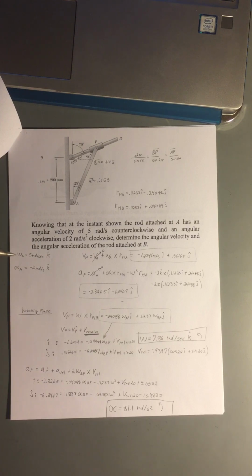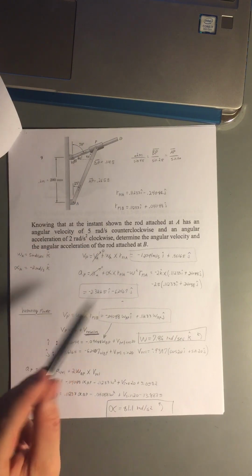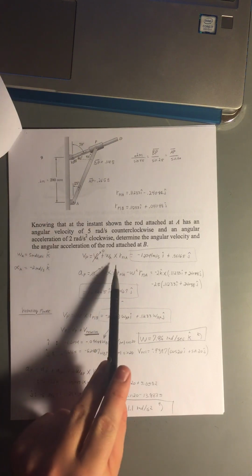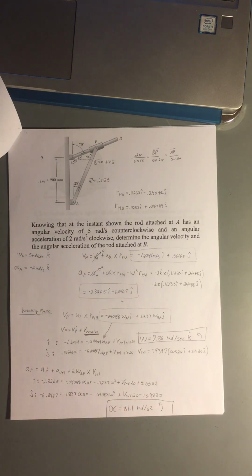And then right here, these are just what was given in the problem, our omega and alpha values for our velocity and acceleration, angular velocity and acceleration. And then this is the equation here that we know we can use for general plane motion, because a lot of the other terms cancel. And then we can also cancel out velocity at A, because we know that this point here at A is pinned. It doesn't translate at all. And so crossing that out, we know that the velocity of P here is omega cross R.